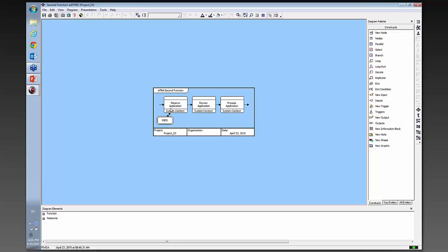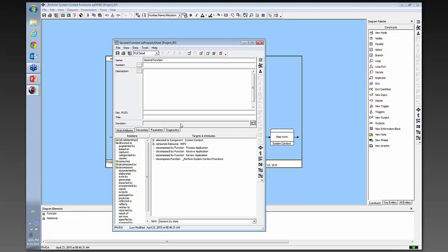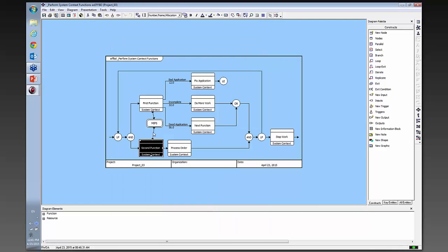I've set it down here as well. And because I have the execute decomposition set to true, it's ignoring the setting for second function altogether. So even though I've set them at different numbers, it's taking the one of the child. It's an important thing to catch, and something that honestly caught me up for a minute until I sat down to investigate why it wasn't behaving the way I'd thought.